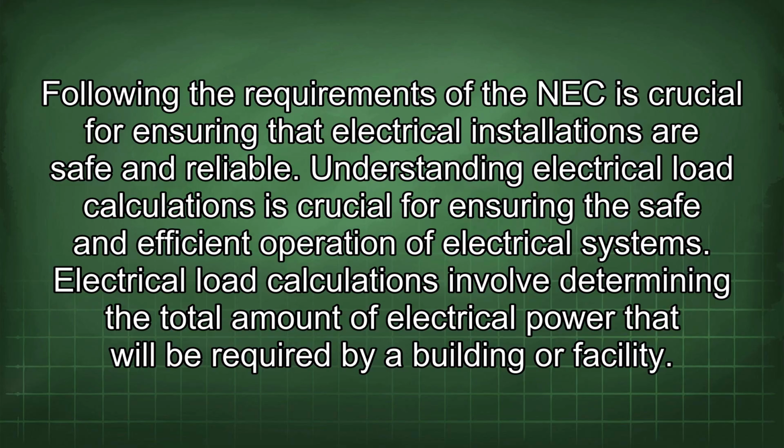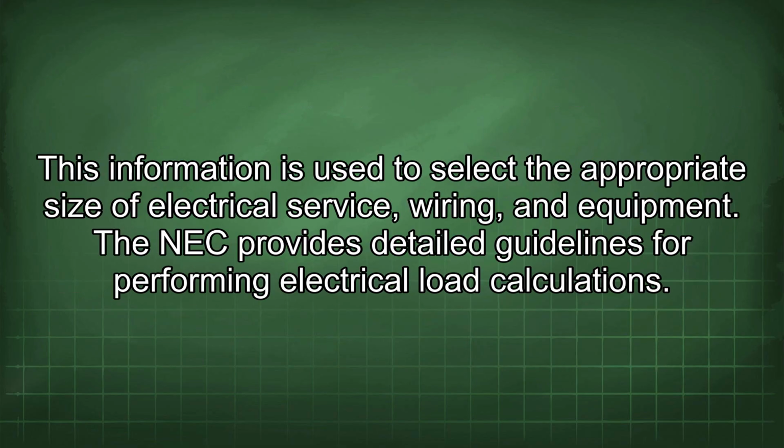Understanding electrical load calculations is crucial for ensuring the safe and efficient operation of electrical systems. Electrical load calculations involve determining the total amount of electrical power that will be required by a building or facility. This information is used to select the appropriate size of electrical service, wiring, and equipment. The NEC provides detailed guidelines for performing electrical load calculations.